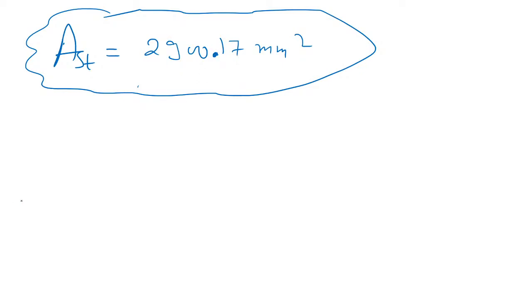So now guys, what you can do from here, each of your designs will be different because all are having the liberty to choose the diameter of their choice. So in order to maintain uniformity, I am fixing the diameter. Let's say we are working with 20 mm dia in case of tension reinforcement.